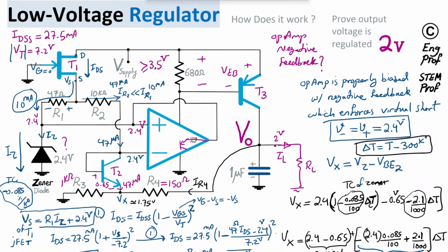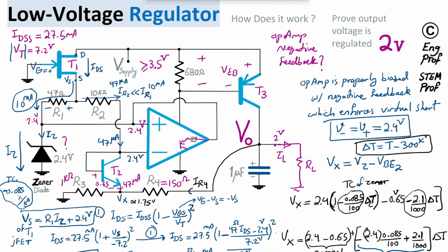The only recommendation that I have is it's important to make sure that especially the R1 and R2 resistors are, let's say, 1% resistors, or better, 0.5%. It's not tough. These are relatively easy to buy kind of resistors. And also R3 and R4 are also 1% tolerance resistors. So the variation is small, not a large one.